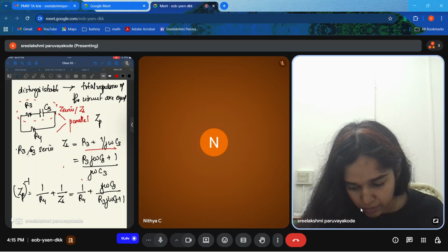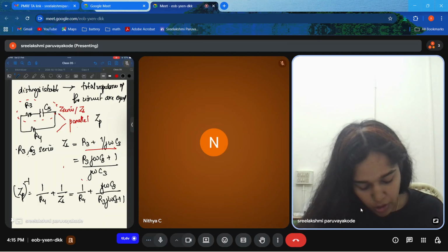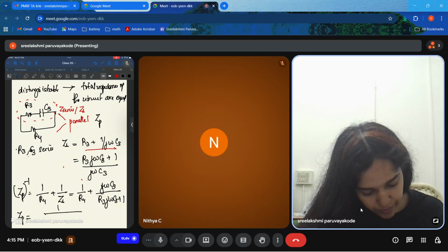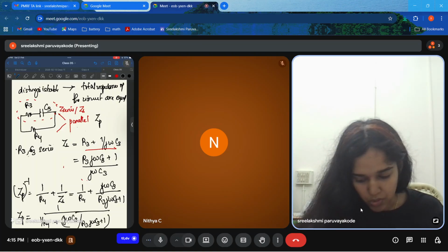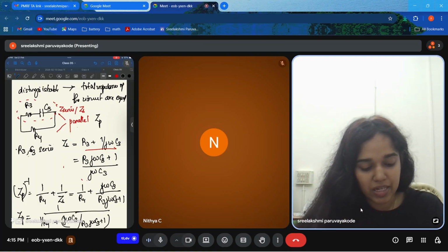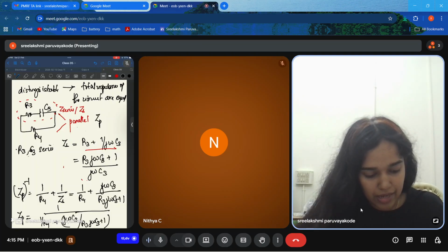Now, what is the Z parallel? It becomes 1 by R4 plus j omega C3 by R3 j omega C3 plus 1. This is one term. Okay. The Z parallel is nothing but the net impedance of the entire circuit.